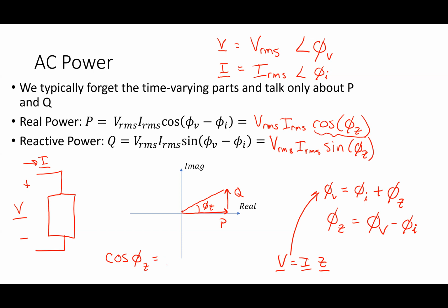Power factor. And what do we like power factor to be? Anybody remember? 1. So we want the angle to be 0, which makes the power factor 1. So what's true about the impedance? If the power factor is 1, the angle of the impedance is 0, so the impedance is a what? A resistor, right? What does that mean in terms of power? That means the only thing that load is doing is work. That's usually a good thing. We just want our loads doing work.